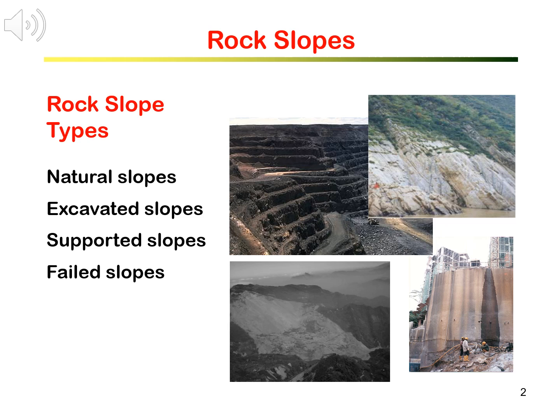The upper left photo shows slopes of a surface coal mine. As the mining is progressively from surface going down, it always leaves slopes around the mine. The slopes in surface mines are typically stepped to provide driveways to get down the mines. Slope stability, therefore, needs to be considered at two scales: the slopes at each step level and the overall slopes of the whole mine.